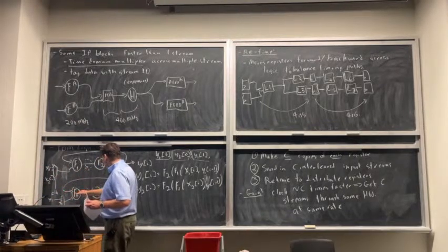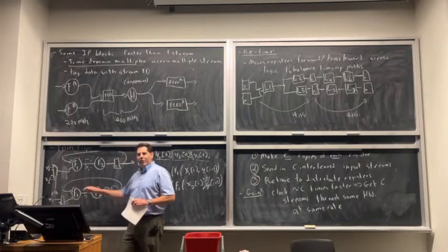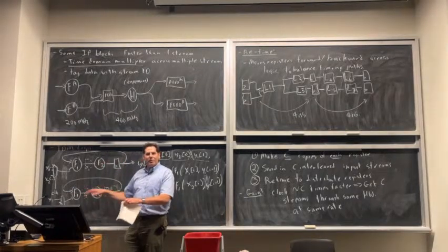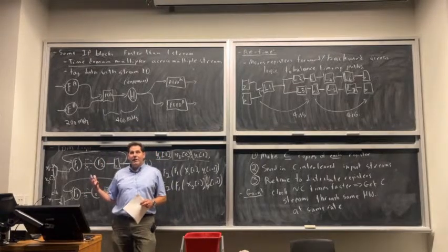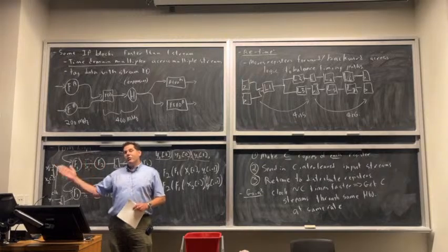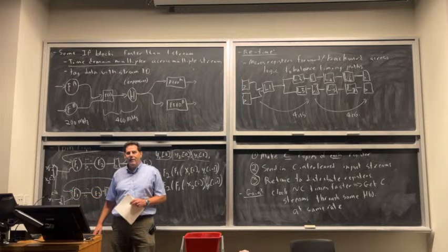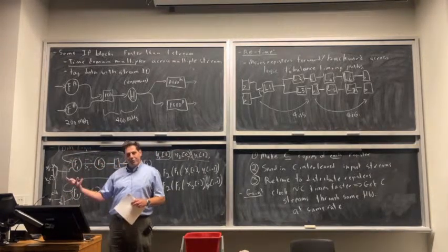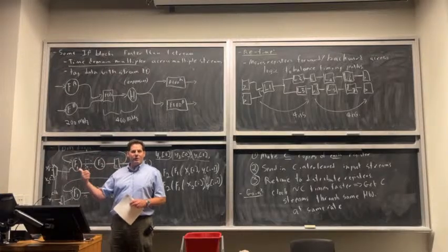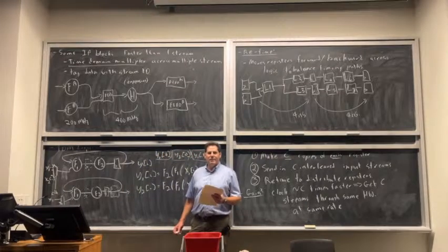Because our whole goal in doing this is to pipeline it, we really have intermediate results from multiple streams in the hardware all at the same time. But from the output perspective, we get a bunch of outputs from different streams interleaved cycle by cycle, okay? And it's a way that we can now pipeline loops. Doesn't help us with one stream, but if we had a whole bunch, it does help us get several streams through the same hardware in less time. Does that make sense?